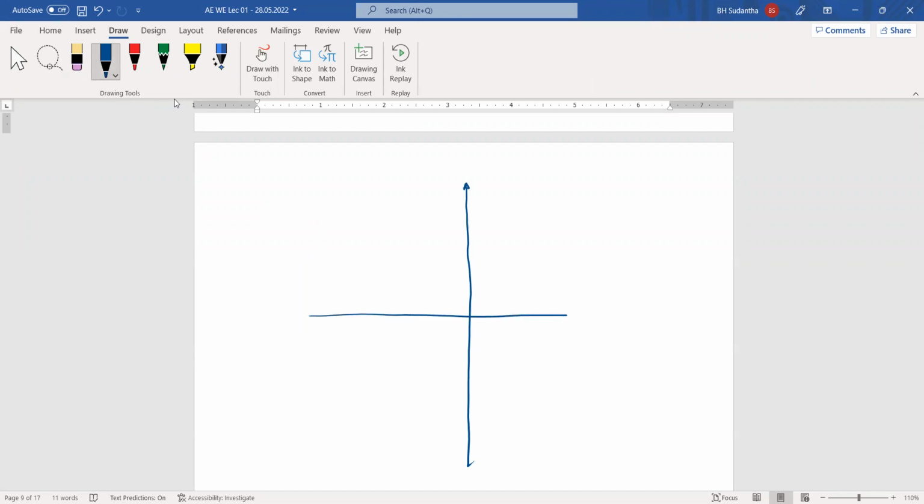for both directions of the voltages. The previous case we drew is the voltage when we apply voltage in the forward direction, and we saw that at first there is no current going through. After that, the current goes like this. But when we apply the voltage in the reverse direction, there is no current going through this one, but after applying more negative voltage, this diode will be damaged.